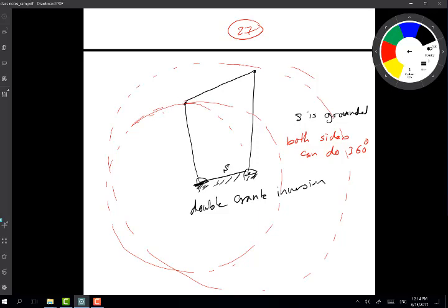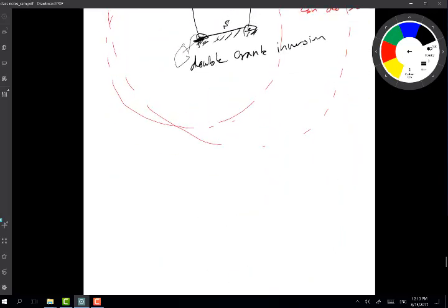In this case, you'll find that it's exactly like two gears meshing together, but the velocity changes. You'll be able to drive one of those links with the motor or whatever, and then the other link will follow this motion, will do 360, and the velocity of the other link will change during the motion. But in any case, that's a double crank inversion. Of course, if the linkage is not Grashof, none of the links will do 360.